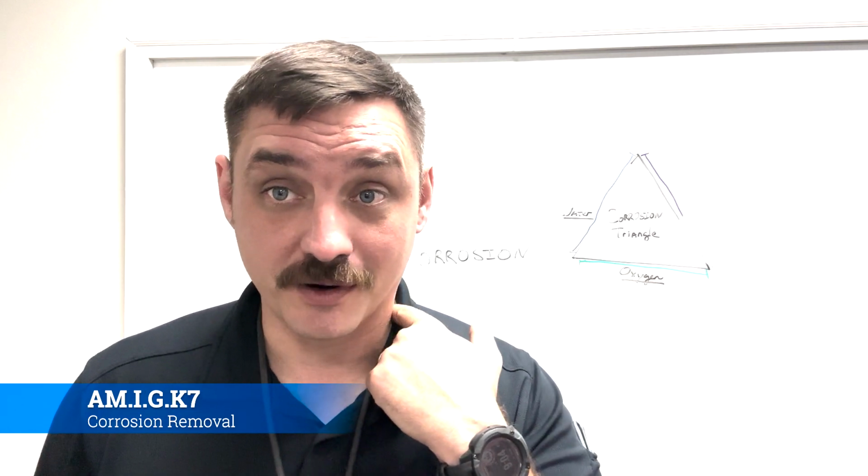That's about the best that you can do. And then we'll monitor it as the annuals progress. And if it gets worse and worse and worse, then it may be time to do something drastic, like replace the wing. But generally speaking, you'll want to try to avoid replacing very expensive parts that are going to require a lot of work, and it's going to be very expensive to just simply buy the part and mount it. But as a rule of thumb, always replace corroded parts if you can.